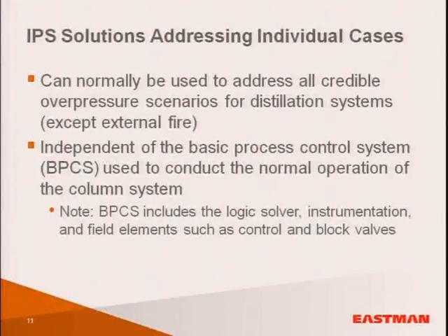And as I said, you can't use it for an external fire, but you can use it to address all credible overpressure scenarios for distillation systems with that exception. It must be independent of your basic process control system that is used to conduct the normal operation of the column system. And in this case, our concern in the BPCS is looking at not only the logic solver, but all instrumentation as well as field elements such as your control and your block valves.